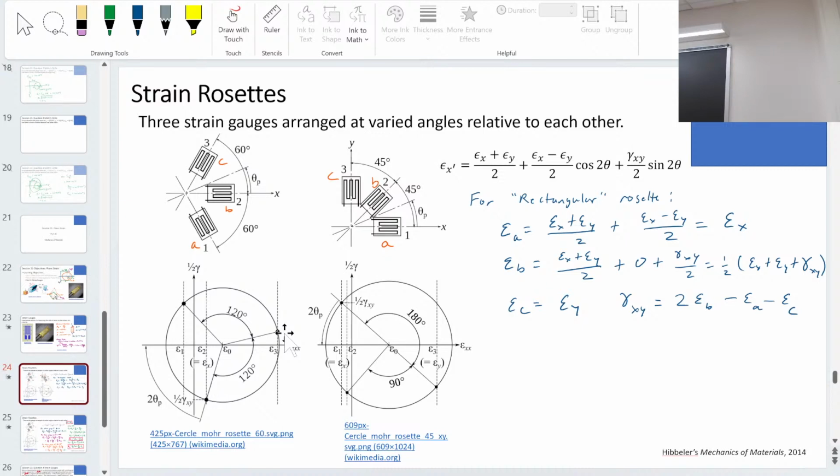First, when we talk about convention, we're talking about the convention for the shear force across the beam, so we had to get that convention right. But then if I take an element where I've got that convention going, and that element has a face like this, the internal shear force is going to be the same, acting over that area, so then I can figure out what the stress would be. If I draw the arrows with positive shear stress up, then the cut should be done exposing to that side.